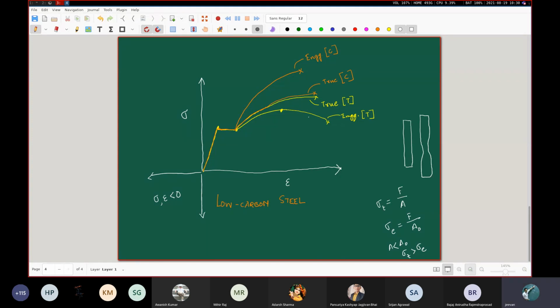Yes, somebody else was saying something. So we can measure ultimate stress point only via engineering stress strain plotted by a tensile test, right? Can it be measured in any other way? Like in the other cases, the graph is only increasing; it's not falling down. Yes, you're absolutely right. The ultimate stress is actually defined with respect to this engineering stress, engineering strain diagram corresponding to a tensile test case.